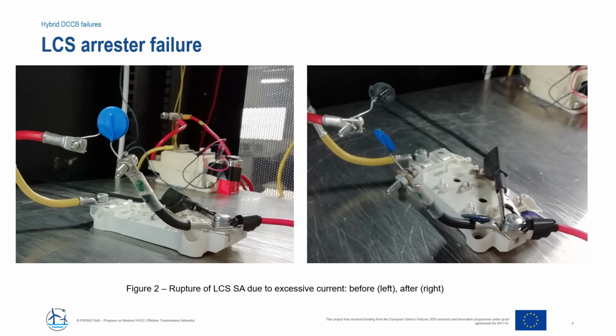Whatever the cause, the UFD is not providing sufficient blocking voltage to protect the load commutation switch. Before the opening of the main breaker, the LCS's surge arrestor is visible as a blue button-like component. After the opening of the main breaker and the de-energization of the test circuit, the arrestor is visibly split in half. So the question is, what happened?